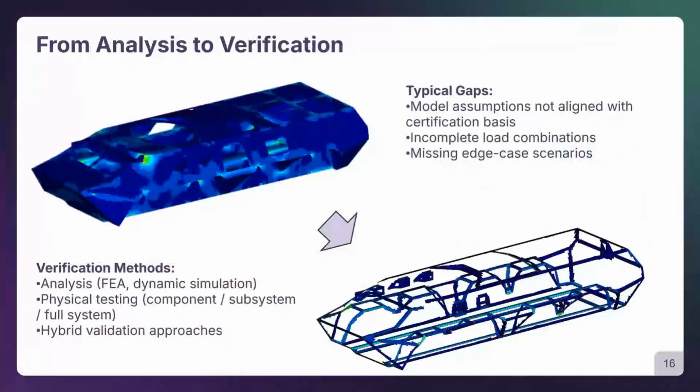Also, even if we have our results ready, so we have stresses, we have some displacement, it doesn't mean that we already have an answer that the structure is actually safe enough to operate, that it meets the mechanical standards and also the specific military standards. Typical gaps are that model assumptions are not aligned with the certification basis. So we always need to be sure that our model actually represents what we need to analyze.